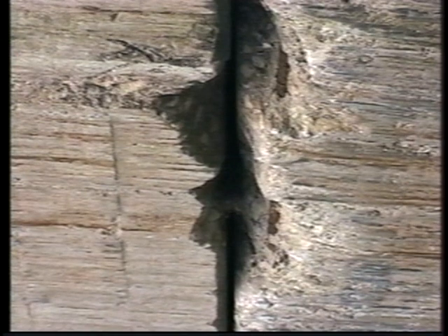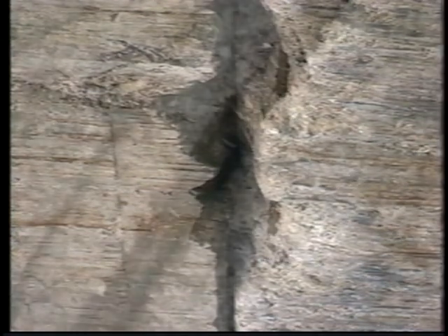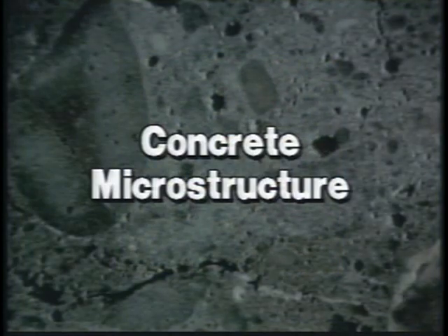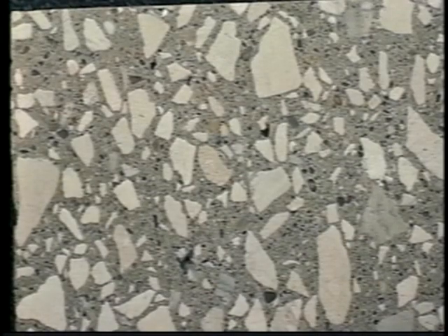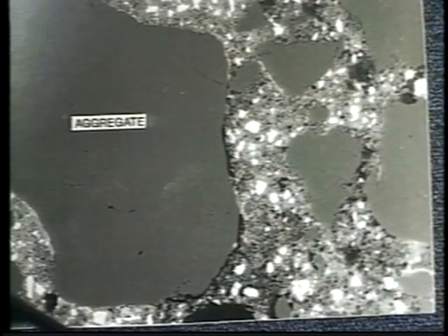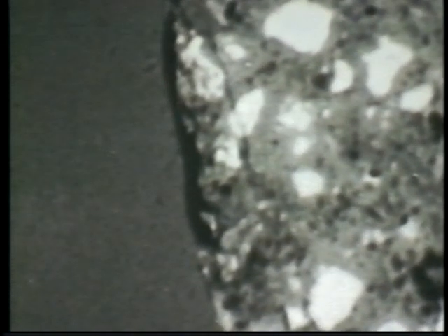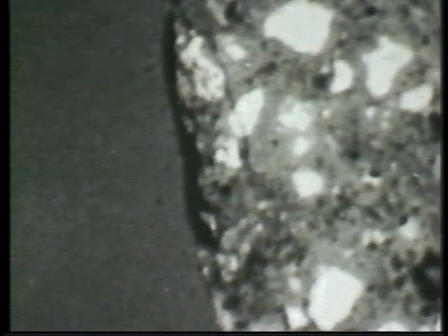If the capillary porosity is well connected, there is an easy pathway for ions from corrosive road salt to reach reinforcing steel in concrete. When water is consumed by the hydration process, the connectivity of the capillary porosity can be lost, reducing permeability. At the millimeter length scale, concrete is a random composite of aggregates embedded in a cement paste matrix. The interface between aggregates and cement paste is very important. This region is called the Interfacial Transition Zone, or ITZ. It is a region of higher porosity, less cement, and more calcium hydroxide.